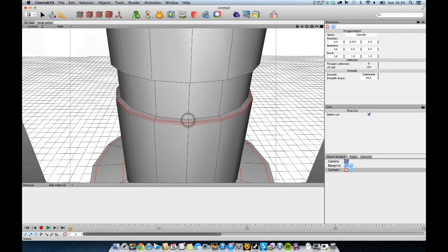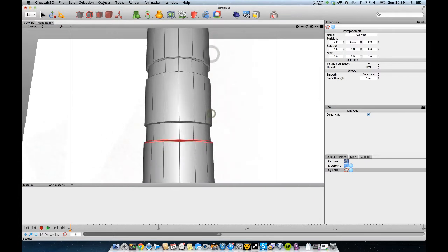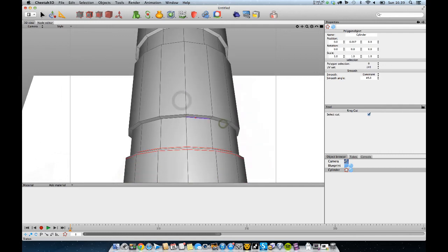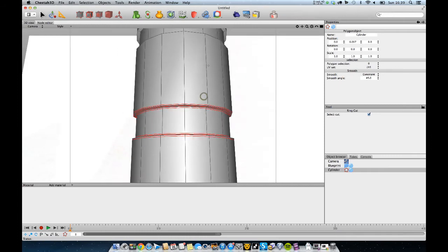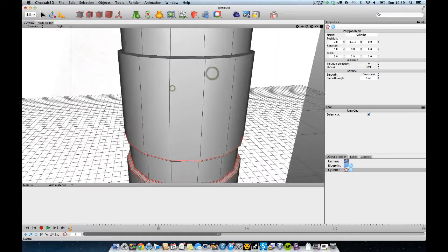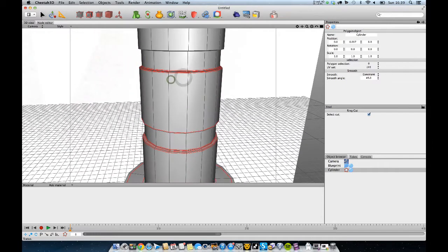The reason I don't use creases and I opt for manually placing cuts is that it gives you a lot more control. Creases are either hard or not. The more geometry you have, the more control you've got. You can move it around, you can soften those edges up a little bit. Sometimes a crease is fine. Also, if you're going to be moving around into different renderers, creases very rarely translate too well. So I just don't depend on them at all if I can help it.